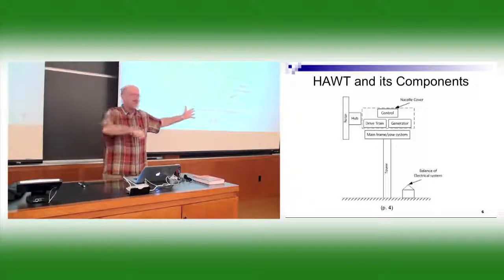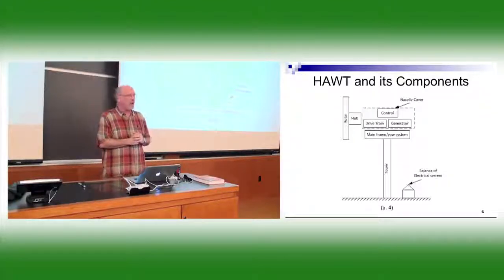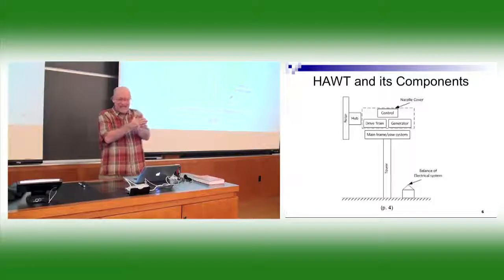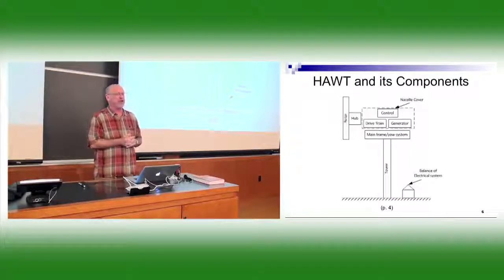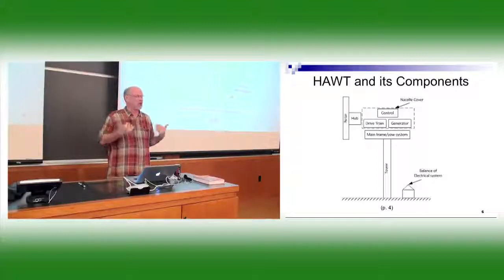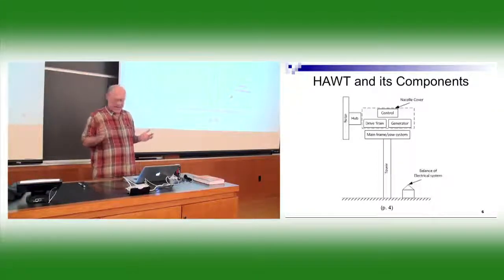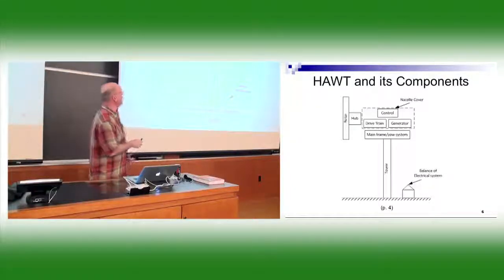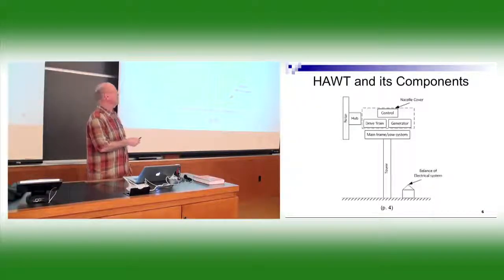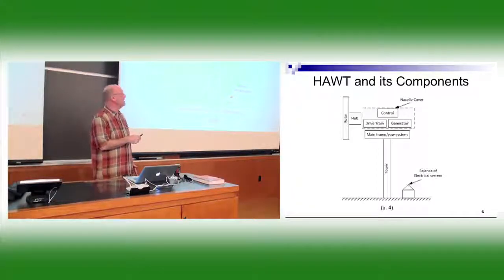This big wind turbine is like a big gyroscope. Although it's moving slowly, it still has angular momentum. And so it's not easy to turn it, and you can't turn it just as fast as you'd like. You have to turn it slowly to keep the loads down. That could be a problem if the wind's changing directions quickly. But that's usually this yaw motor, and how fast you have to yaw this machine designs everything up here. The weight of the system, how big the tower has to be. So everything is about that.